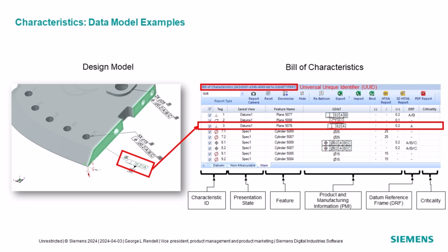Earlier in the first session, I think, Daniel, that you kicked off today, you talked about the word features. Features gets us a little confused because traditionally in MCAD, our definition of features are different than manufacturing or quality definition of features. So I'm going to try to avoid using the word features, but the key thing from my perspective is the associativity and the links. These things do not have to be one-to-one, they could be one-to-many. Both from the geometry to the PMI back to the geometry, the PMI to the characteristics that will be new in NX, and the characteristics back to the PMI.